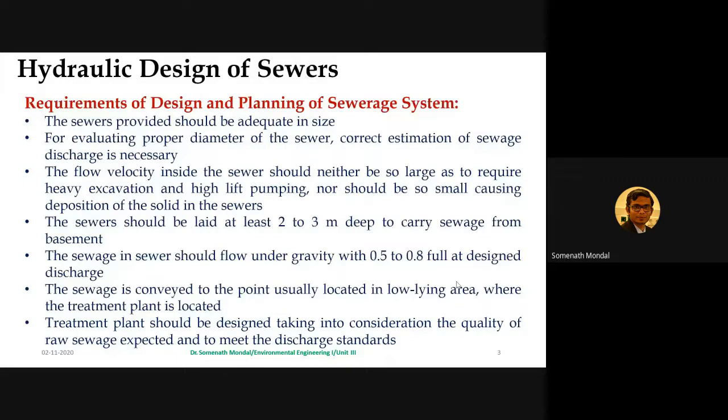The flow velocity inside the sewer should neither be so large as to require heavy excavation and high lift pumping, nor so small as to cause deposition of solids in the sewers. You need to imagine this sitting within the sewer lines itself, otherwise you will never understand. If you need high flow velocity, then you need some extra power to generate it, and that can be done only with the help of a lifting pump.